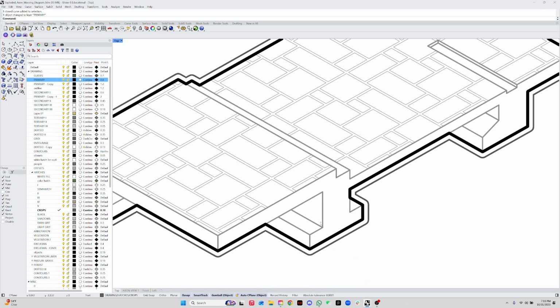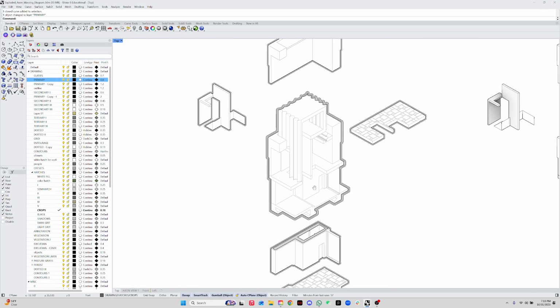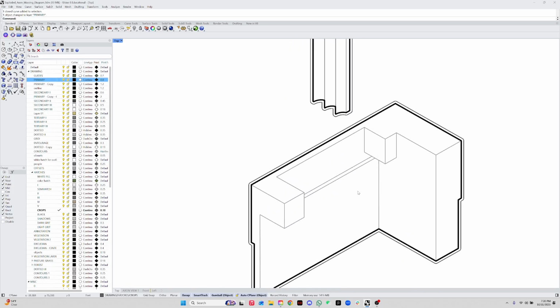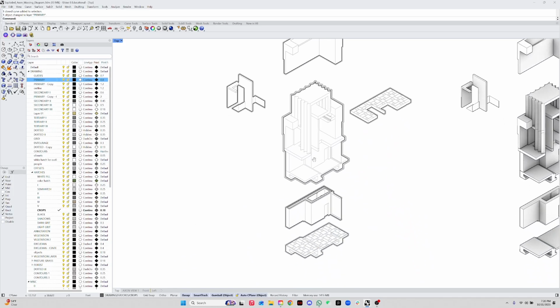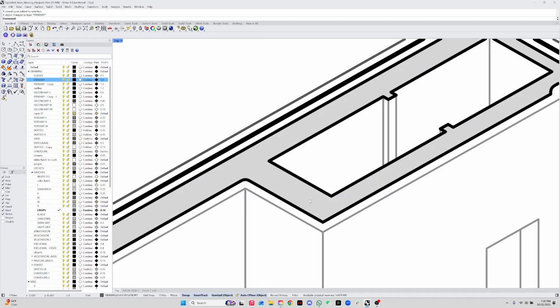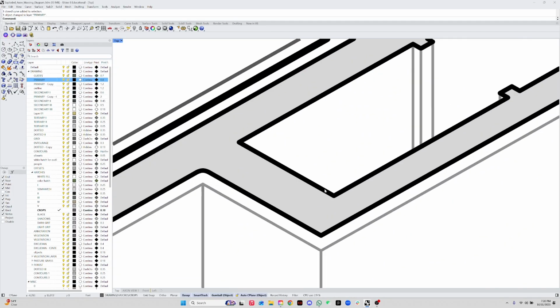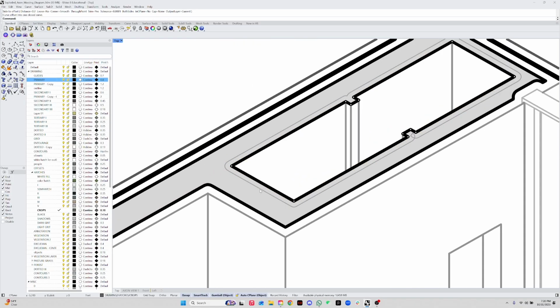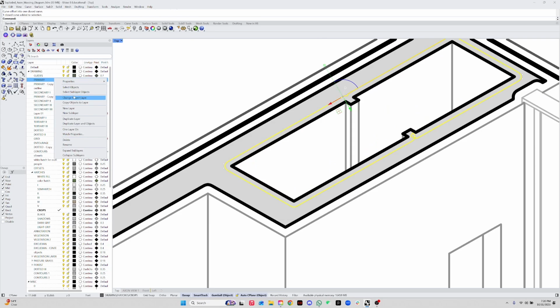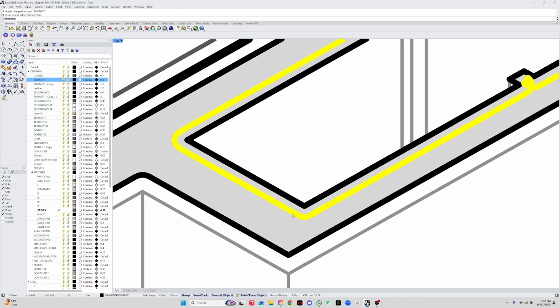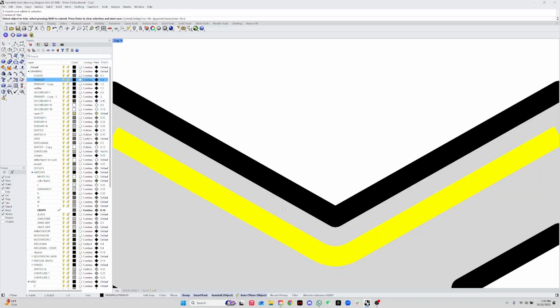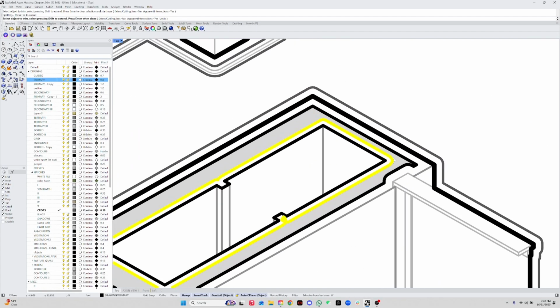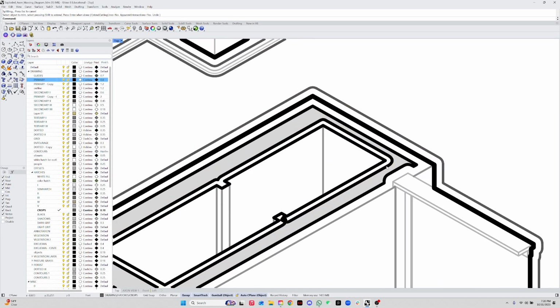You can even do that in the floor slabs when you're doing it, or you can just keep it consistent and do it on the walls at the top and specific areas. Graphically, you can do that and it will look nicer. In this one, I probably would like to offset it actually. Let me offset 0.2 maybe, a little bit less, and then do the same line weight, the primary that I was using, and then do the same thing again, trim. When you trim hatches, you have to just click the line that you want to trim from, and then trim along with it.